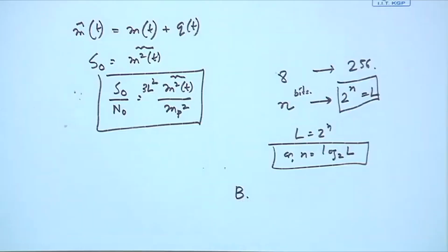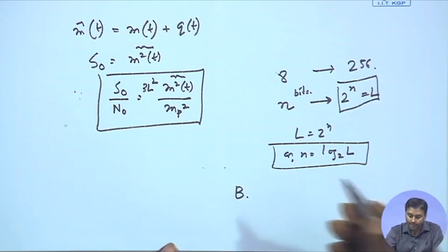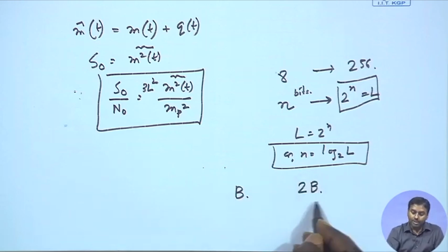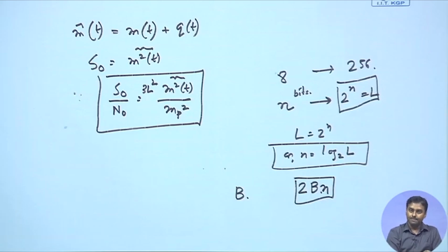Okay. So, basically I had B, that is the overall bandwidth. I could eventually transmit 2B samples, okay. And overall how much information am I getting? For this B bandwidth, because of Nyquist sampling, I am generating 2B samples, because that is the sampling rate. Each of those samples is now represented by n bits. So, this many bits I am representing.